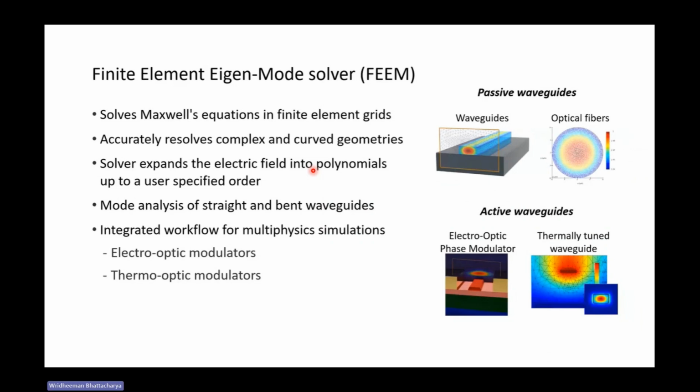As we can see, passive waveguides such as optical fibers and waveguides, and active waveguides such as electro-optic phase modulators and thermally tuned waveguides can also be simulated on the principle of finite element eigenmodes. This offers two types of algorithms, so according to the user, they can use any one of them as they wish.